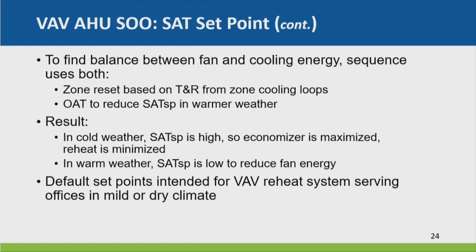How many people know what trim and respond is? Okay, one or two. I'll talk about it in more detail in a minute when we talk about static pressure set point reset, but it's basically a way of figuring out, like in this example here, what's the warmest zone that'll satisfy the zone that needs the coldest air? How do you know this? Well, in a computer program, it's real easy. I calculate the load in the zone, I divide by 1.1, and the maximum CFM of that zone. That gives me a delta T. I subtract it from the room temperature. Oh, there I go. I need 62.1 degrees to satisfy that zone. And now I know my set point is 62.1.